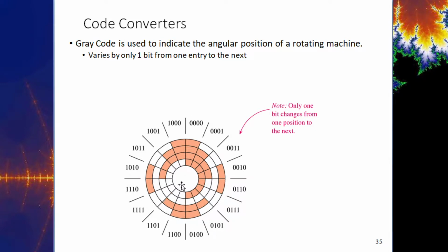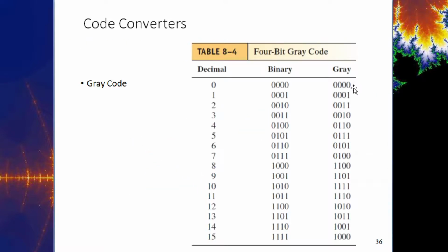Sometimes they'll shine a light from the other side, and the receiver on the other end will detect what pattern of these is turned on and off, and it will know what step in the sequence it's at. You can see there's a difference between gray code and binary code. I'm not going to make you count in gray.